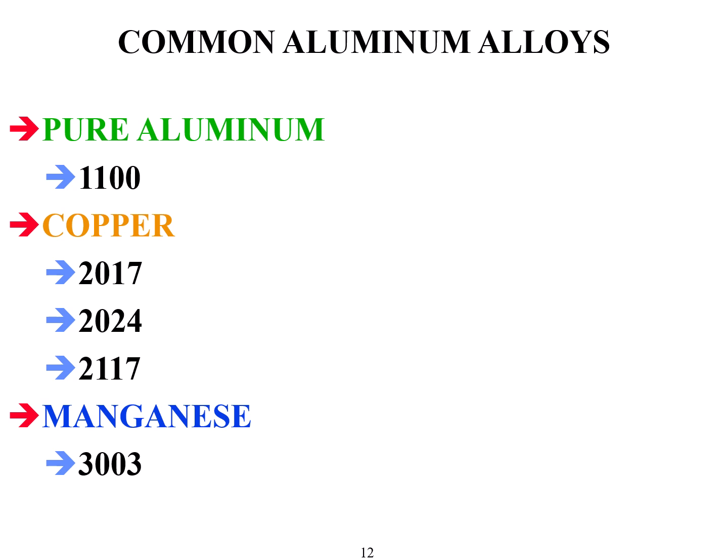There are others such as manganese, the list goes on, and the reason we have all of these varying alloys is if we've got an alloy sheet with a copper primary ingredient, it makes sense to create fasteners with the same ingredients. That way we can avoid the potential for galvanic corrosion. So for every sheet that's produced, they're also going to produce fasteners to align with those alloying ingredients so they'll play well together over the long term.